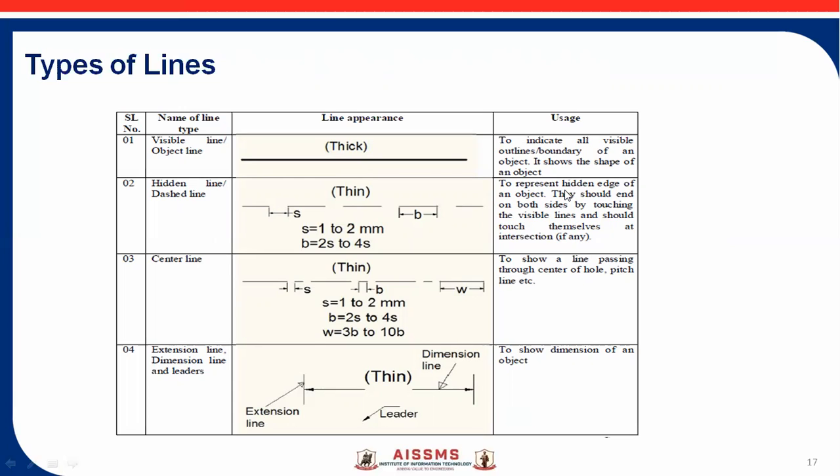Then, to show the hidden parts, the dashed lines, the parts which are not visible to your naked eyes in complicated objects or complex shapes. You can show things like this, the dashes, by using an H pencil. Thick lines or visible outlines you can draw with the HB pencil, and thin lines, or the hidden lines, you can show with the 2H pencil.